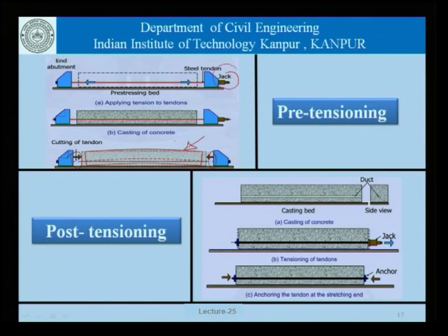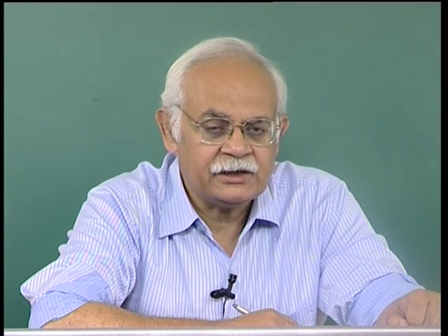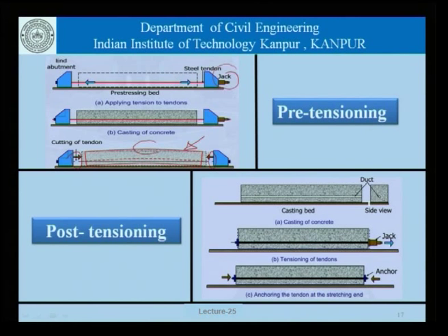So, basically what is going on is the fact that concrete, if it was not reinforced, would like to go back to its original position, which is something which is prevented by the presence of steel. And since the degree of restraint at the top surface here is smaller than the degree of restraint at the bottom, the beam tends to hog. And if this hogging is not controlled, we could have cracks initiating at the top the way it is shown here.